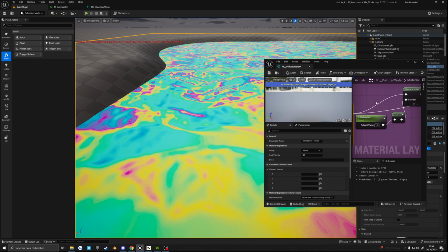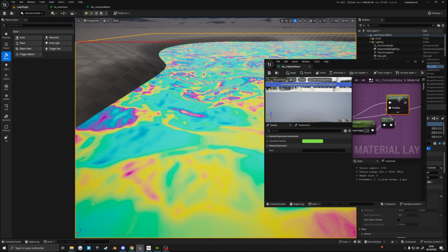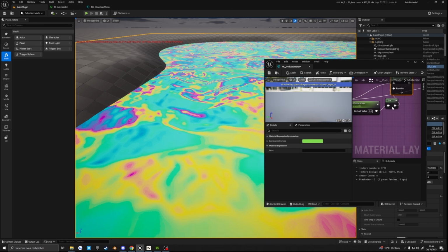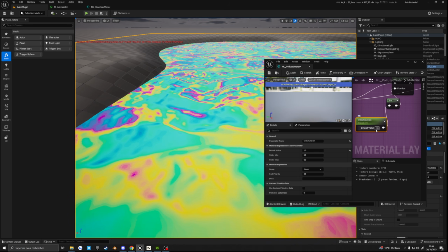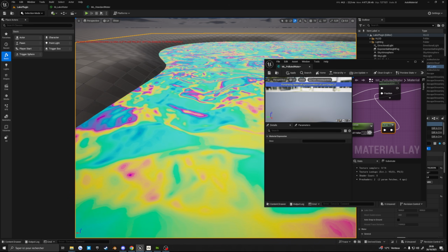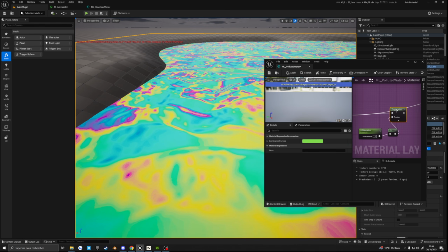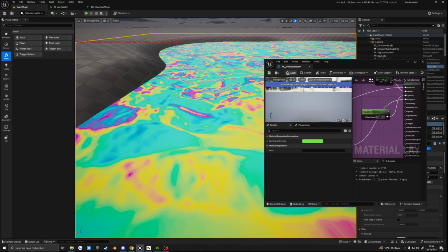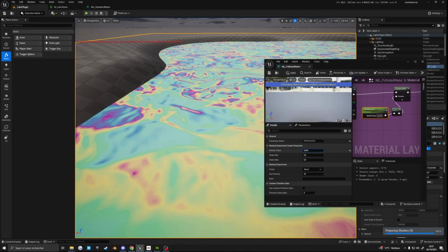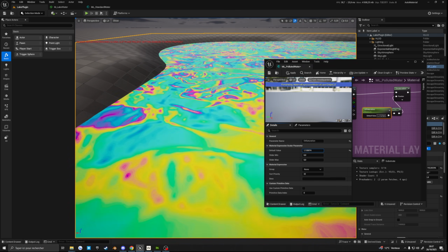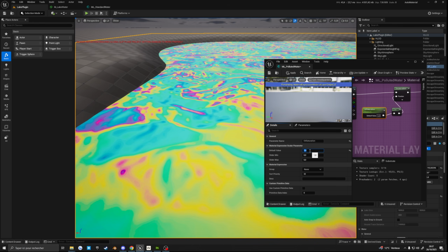And after we take the RGB result, we are adding a desaturation node, and then we add a parameter node. We do 1- it to invert it. So we actually have a saturation node. We plug that into the fraction input. And then after that, we can actually plug that into the base color. And so using the saturation, I can actually have lower saturation on my color, or I can even have more of those. But I like to keep this at 1.